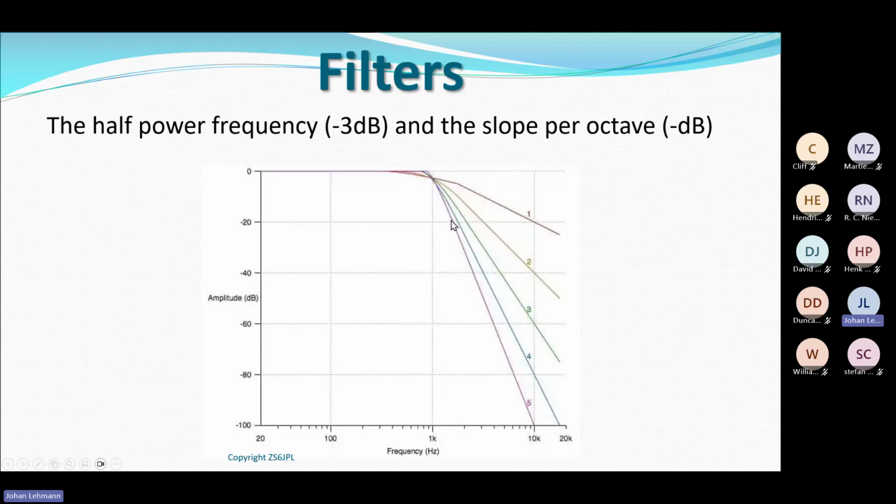So if you look at this filter, this is a fairly lousy filter, number one, because its 3 dB point is, I see they've put all of them at the minus 3 dB point, 1 kilohertz. But if you look at it over an octave, it's only got 20 dBs of attenuation. This low-pass filter is a lot better. It's sitting on 40 dBs per octave. And this is normally dependent on how many inductors and how many capacitors I use to make up my filter and the configuration of the filter.